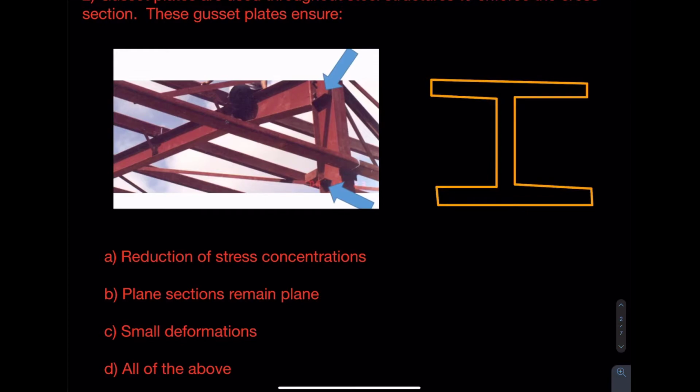So if we look at the beam in the picture, of course, it will have loads going down as follows. So I'm kind of drawing them in the pink. So what's going to happen at the bottom is this bottom flange of the beam is going to start making contact with the column. And from that, it's going to start transferring its stress into the web of the column.